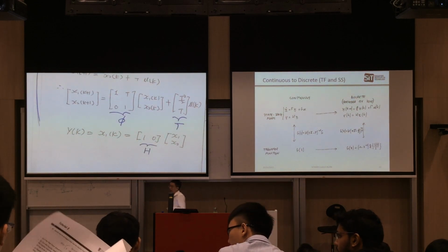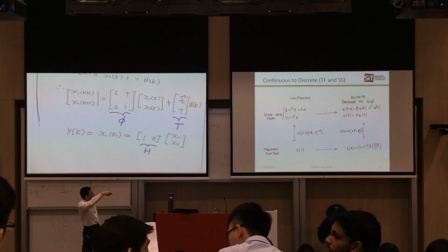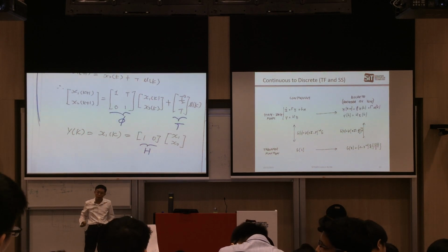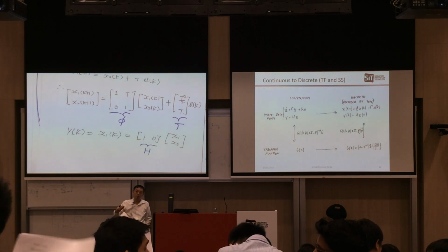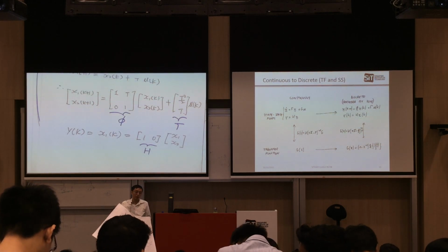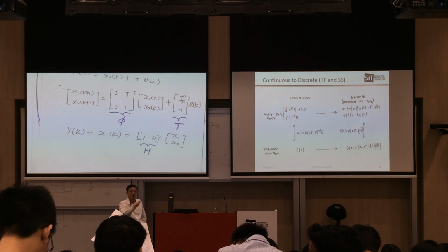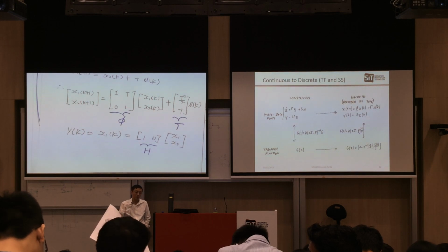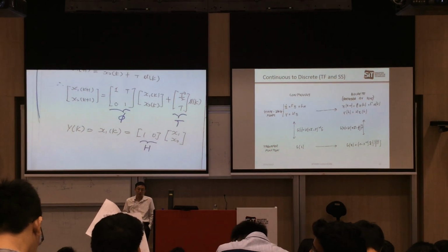And similarly for the digital one, in your difference equation, you have many delays. If you are nth order, you have n delays. Then your n delays will convert to nth order matrices, or nth order vectors. So here you will also see your vectors are 2 by 1 and your matrices are 2 by 2. If your transfer function is third order, fourth order, nth order, then you will see your vectors and matrices will be nth order. Okay?